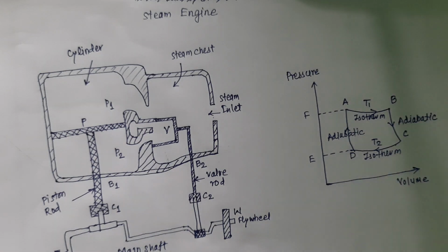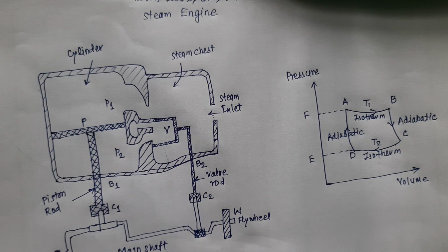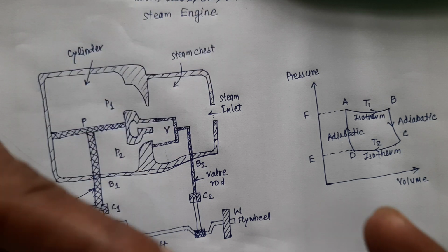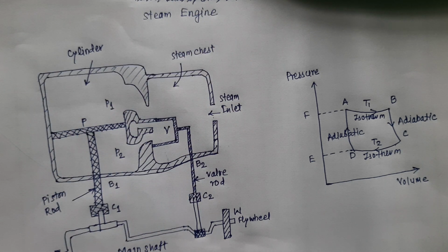The piston and the sliding valve are connected to this main shaft eccentrically at diametrically opposite points such that they move in opposite directions when the shaft rotates. The main rod and the piston rod are connected in such a way that the linear motion of the piston rod is converted to circular motion of the shaft. V is the sliding valve.